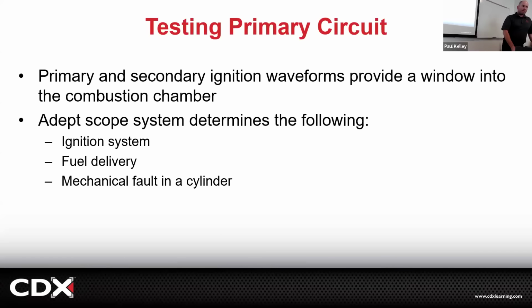And also, this is crazy, but if we actually measure that waveform, we can interpret it to tell us if it's an ignition problem, a fuel delivery problem, or a mechanical fault. All right, so in my time, we didn't really get that good at these. But in the time before me, without the scan tools and whatever, there were some old school techs that were like magicians.